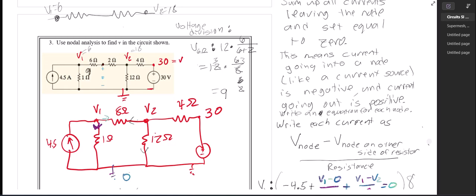I want to know what is the voltage right here, and I found that the change across this resistor was 9. So what is this V right here? It's 15. Because going from 6 to 18, I have to be going up. So I'll be adding 9 to get 15. So 15 volts. It's 15.